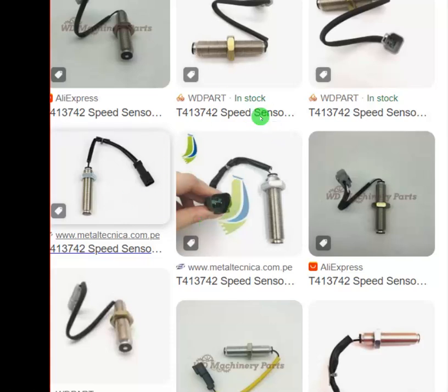This is a speed sensor. We also call this a magnetic pickup. We use this to control speed for generators, for the prime mover of equipment, and so on. For those of you who did the ATS class, we also know about this sensor because we treated it when we were doing our ATS. I know you'll be familiar with this.